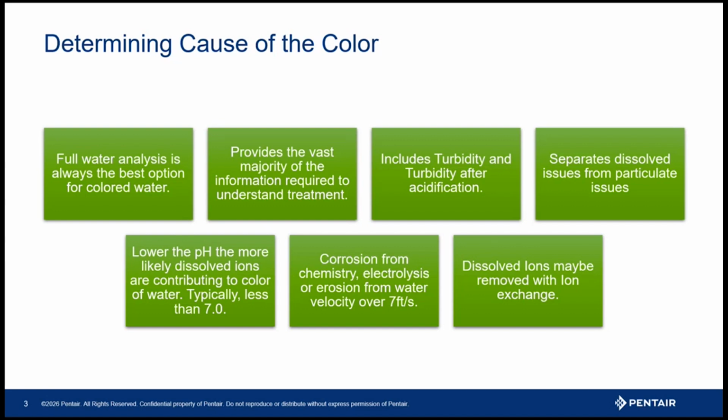If you're going to have properties that sit for a long time with softened water in them, you're going to want to flush those lines before use. And then you may have corrosion in the water just strictly from water chemistry, whether it's low pH, high amounts of dissolved gases in the water, whether that's CO2 or dissolved oxygen.